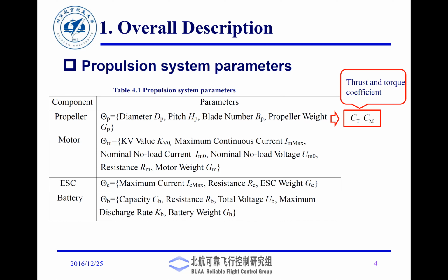If the system sees, there is something called the air data attitude heading reference system. So this is like a barometer, IMU, all that stuff. Basically it says that if delta H is very quick, then it will control the rotor speeds so that the vortex ring state will be avoided. But Bell 609 is a variant of Osprey. So they learned the issues from testing, and they improved that. If you have YouTube videos on vortex ring state, it's an interesting phenomenon, and that was a major cause of the initial V-22 accidents.